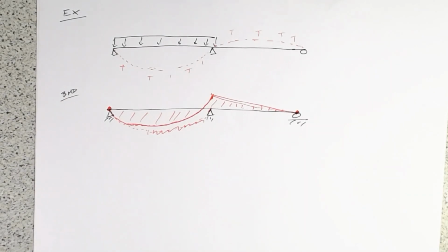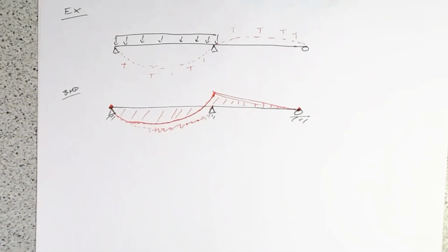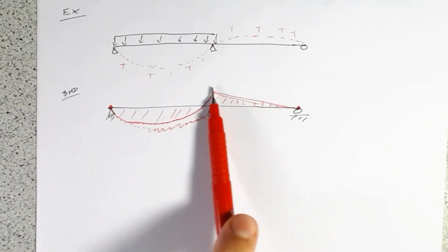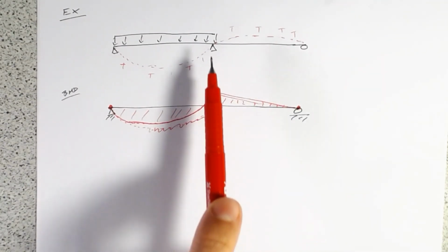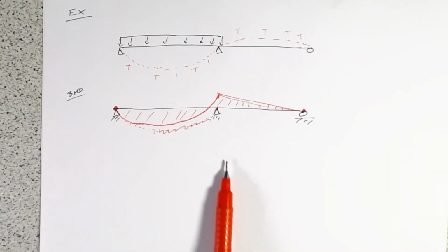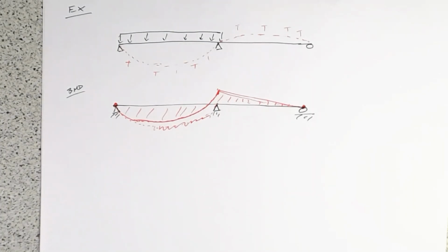So I hope those examples and some of those rules were helpful and informative. Again, the best thing to do is draw the deflected shape as best you can. Look at your rules, know things like when your moments come back down to 0. And then really think about the structure, and think about, if you're going to have bending, you need to have a moment applied. And that's it. I think maybe just one more tip is anytime you've got a support or a discontinuity, where you're going to have a big shear force, you're likely to have a big peak in your moment diagram.